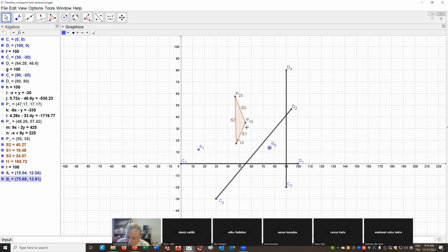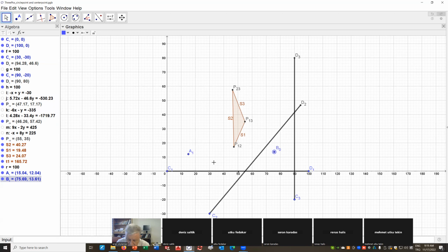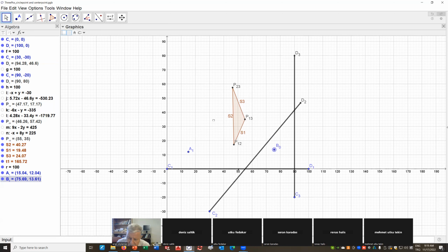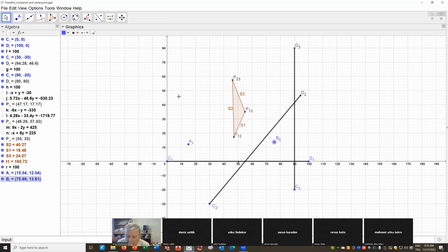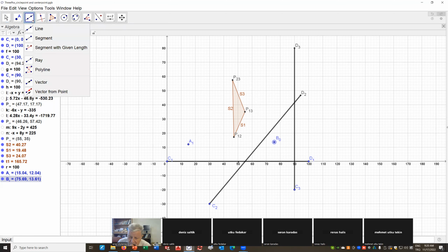For these three positions, this is the pole triangle. I'm not going to repeat how to draw the perpendicular bisectors. It's that simple. Now I want to determine A0 and B1. To determine, first let me start with A1.